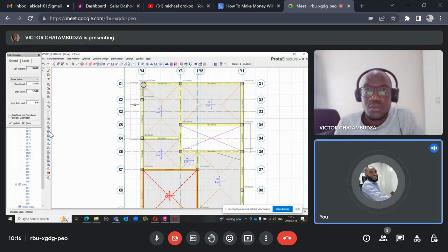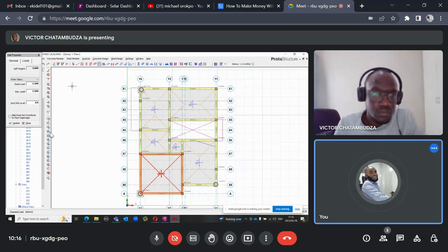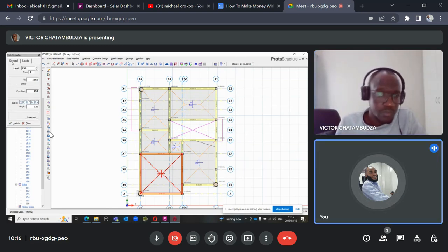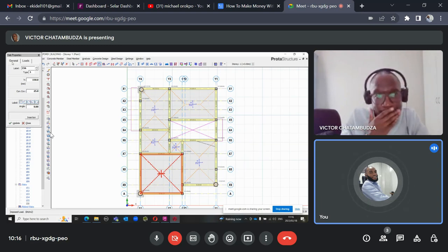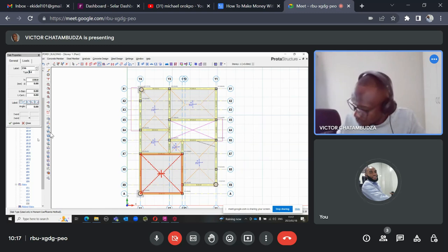So right now, go back under your slab properties. Click on general. Now to put your cantilever slab, click on that place that shows type. You can see type there. Click there and choose type 12. Type 12 is for cantilever. Okay, so type 12 is cantilever.